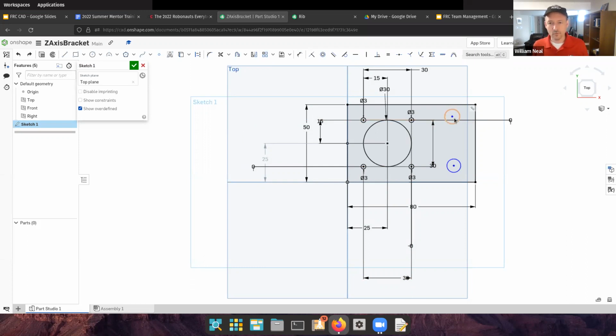Okay, so now there are only 2 more holes. I'm going to specify the dimension of these holes. Just remember my dimension tool. First of all, they'll be vertically aligned with a 0 millimeter difference so that there's a vertical between them. And they should be about the same distance away from the center line. So let's make whatever this distance is, that's 17, I'll just call that 15. And maybe I can make the length of this line 30 then. This is arbitrary. These are just 2 screw holes to hold the component on the linear rail, so the exact location doesn't matter.